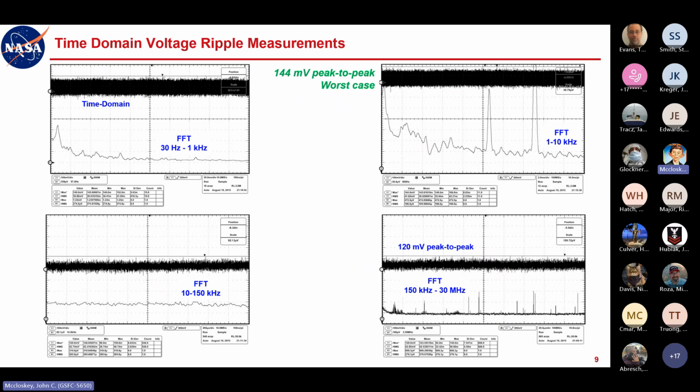Once you instrument all this, once you make the decision that you're going to set up to measure voltage ripple, which is really the main thing, like you actually have a requirement to verify with this, then I said, well, I want to measure those inrush transients. We're already instrumented to do it. We have to turn boxes on. There is no additional time required to do it. So that's just the order of operations. I'm just presenting these data first, but we'll get to inrush here in just a moment.